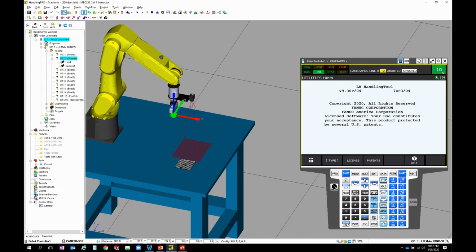So here in RoboGuide, I currently have the robot moving in the world frame. You can see as the Z axis in the positive direction goes up and the X positive direction moves forward. If I switch this to the tool that I've taught, which is tool 2, which I'm currently in, and let me shift my coordinate to tool.